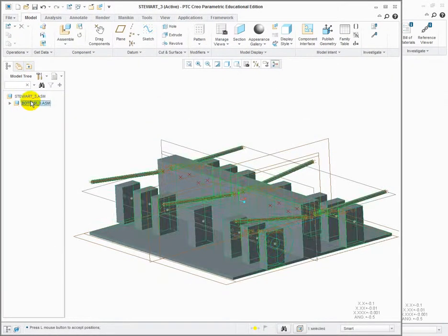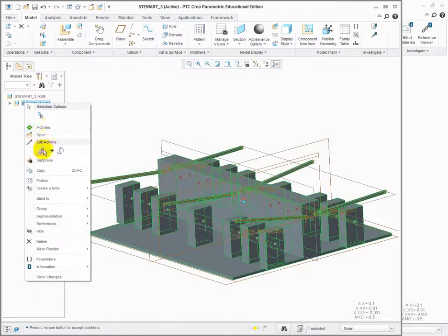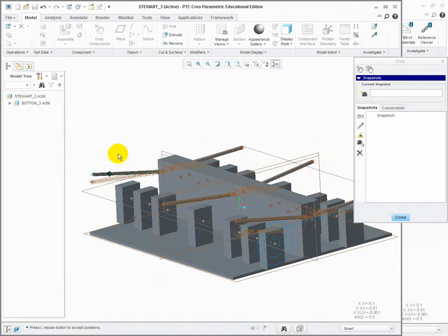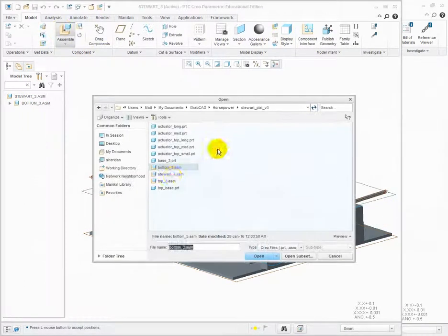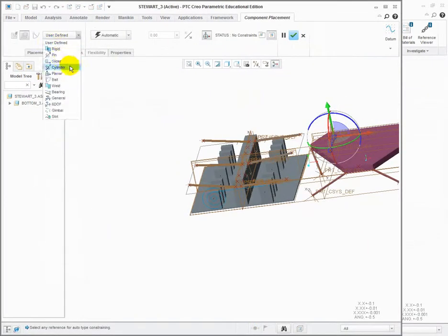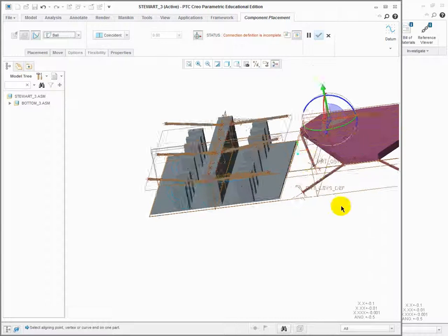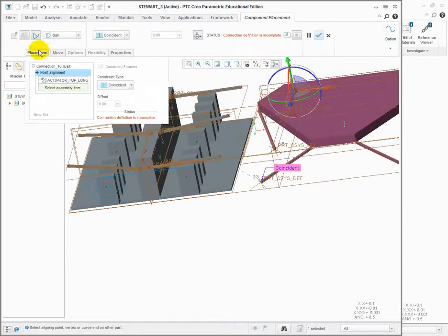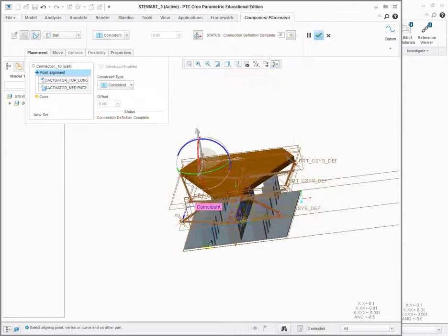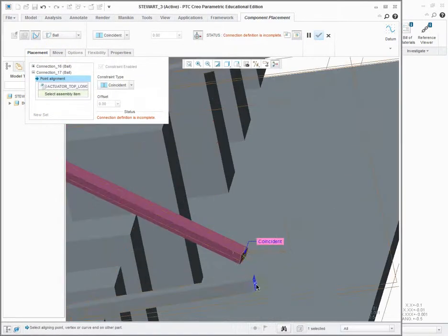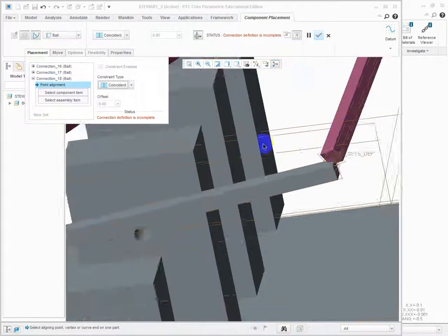There you go. So first I can just assemble this. This bottom one is assembled as default. But even though it is default, it still has all the mechanism constraints. Here I limited them by like 15 degrees. And then I can assemble the top. Just add ball joints everywhere. I want to make sure I can see the actual points. Open up placement. Make a new set. Automatically has ball. New set.